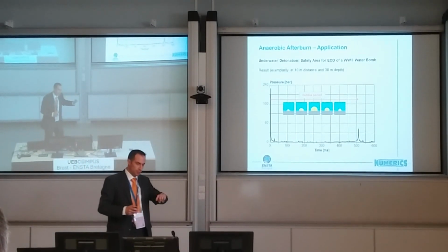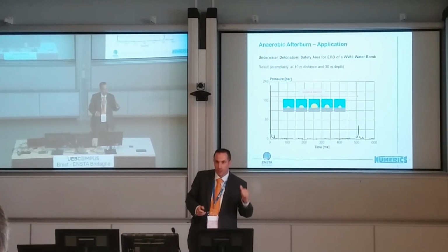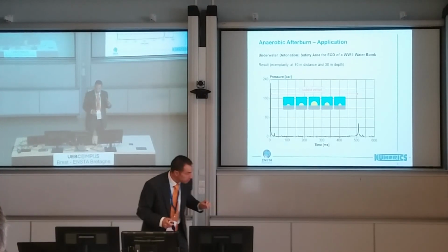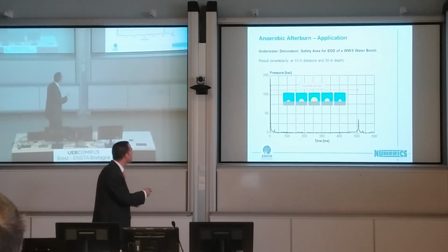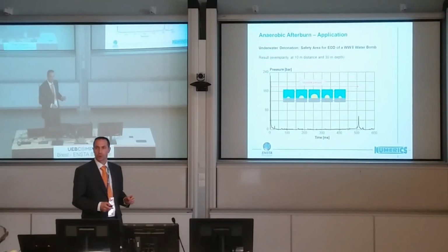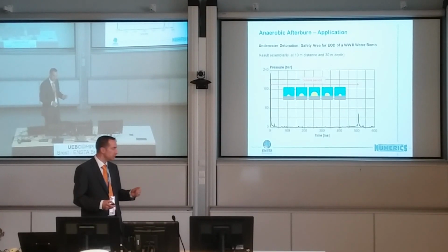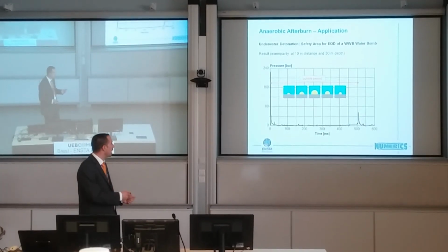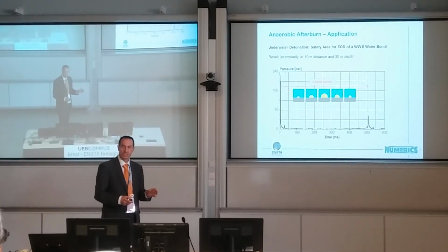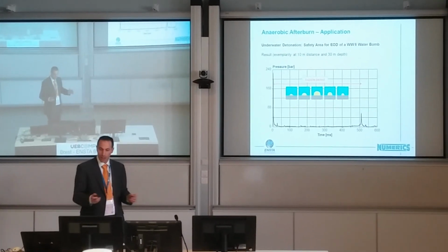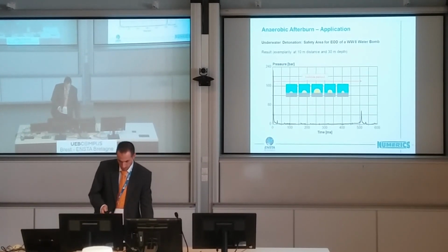So if you want to calibrate your Miller extension, this type of underwater detonation experiment is very valuable, since here you really have data you can work with. There is no disturbance by the existence of air, and the additional energy significantly influences the bubble extension and bubble period. And here you have something to work with.